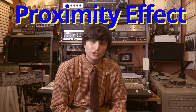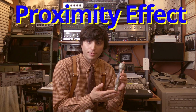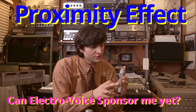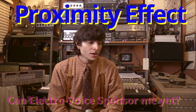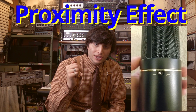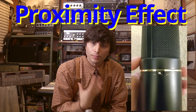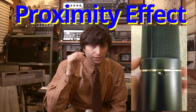Microphones can be designed to minimize this effect as much as possible. A great example of a microphone that I talk about all the time is the EV RE series with the variable D slot, which minimizes this effect. There are also microphones that have a bass roll-off switch that you can turn on if you want to close mic a sound source, and you don't want the effects of the proximity effect.